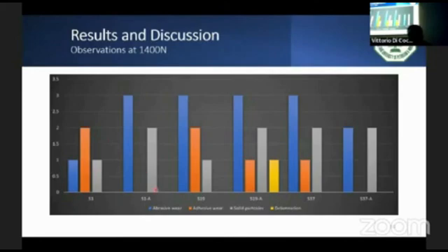After we add the penetration rate, the adhesive disappeared. We didn't find any adhesive, and the abrasive and the solid particles increased. In S19, we saw the abrasive both without and with a penetration rate, and the adhesive decreased. We also observed delamination.